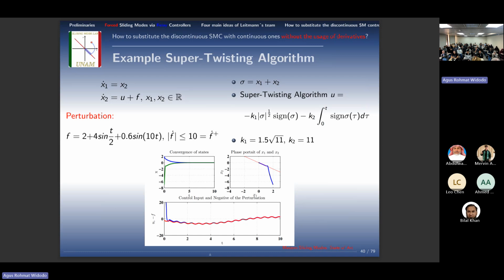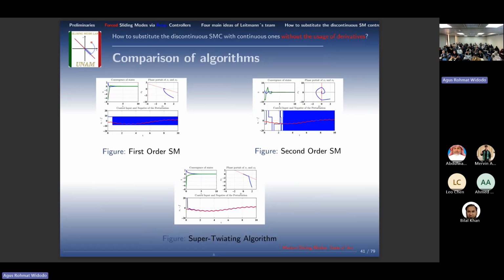And you see the same story here. First generation, second generation, third generation. Practically no chattering. The same story. You can choose a surface, you can approach the surface practically without chattering. It will be second order chattering with respect to discretization, but not the first order. And you see here is the first order. That's the difference between here and here. It's the same system.